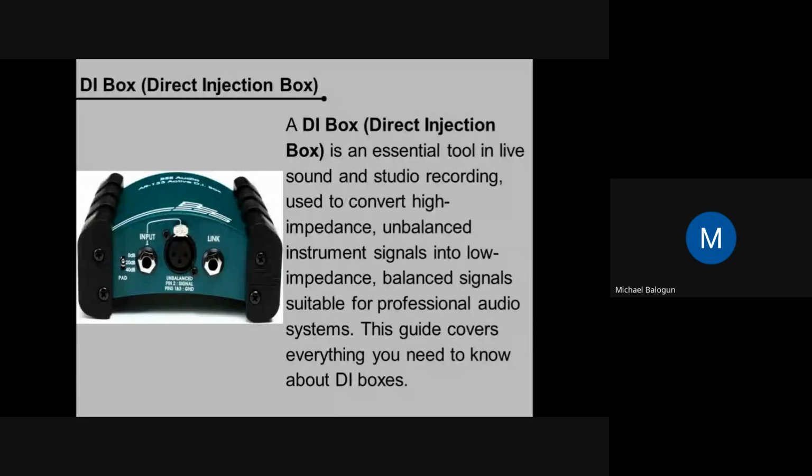That's why when you use a microphone directly on a mic port, once you change it to line, you see that it becomes louder. So that's just the difference. This one has a mic and a line. Once I switch it to line, the signal will just increase. But if it's on mic, whatever I'm sending is what is coming out. With line, it's like times 2 or times 3.